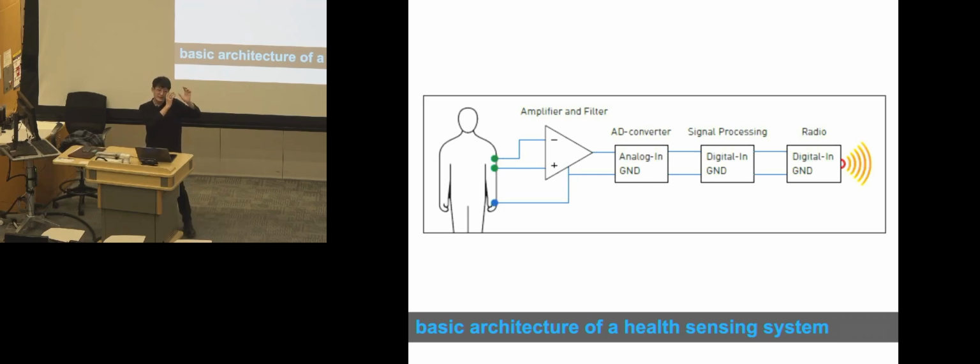It could be taking a look at the signal that you inject into it, or it could be the signal that's originally there. And then that goes through some type of amplifier and filtering systems to narrow down exactly which type of signal you're looking for. And then it usually goes to ADCs, because, for obvious reasons, we have to convert those signals from analog to digital in order for your devices to better analyze them.